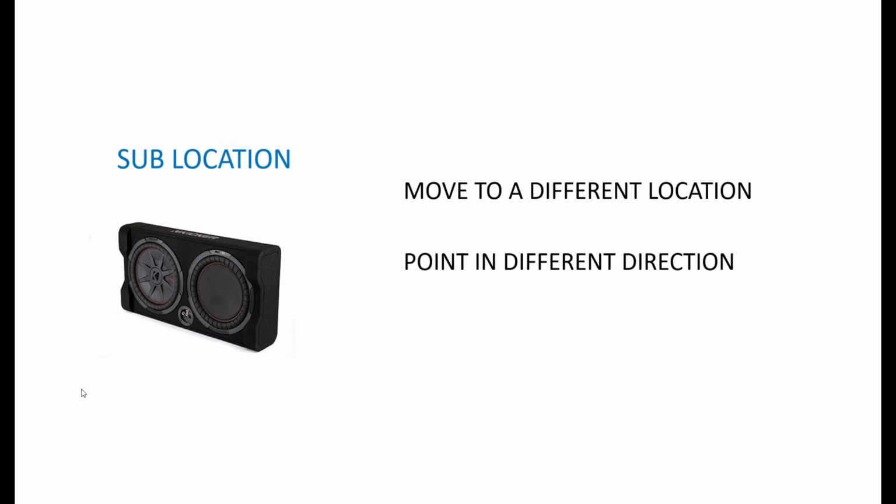The second thing to do is to point the sub in a different direction. So you might have your subs down firing or up firing or firing towards the cabin. So changing the direction that the subs are pointing, equivalent to aiming your tweeters, so to speak, may have a different effect at the listening position on the bass.